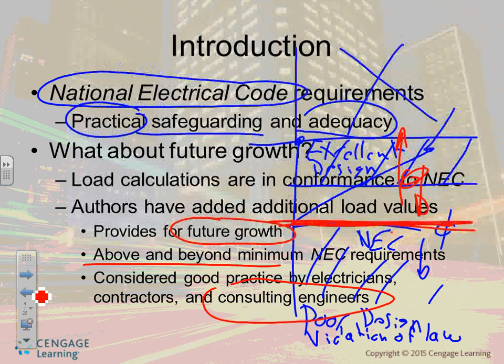We, the engineers, plan for future growth. That's why you put yourself in an excellent design. Don't overkill. A good example about overkilling: a good design is to grab your conduits, and if you have mechanical equipment, air units, chillers, and what not, one pipe per mechanical equipment. Okay, that's a good design. Now you're in the excellent design.